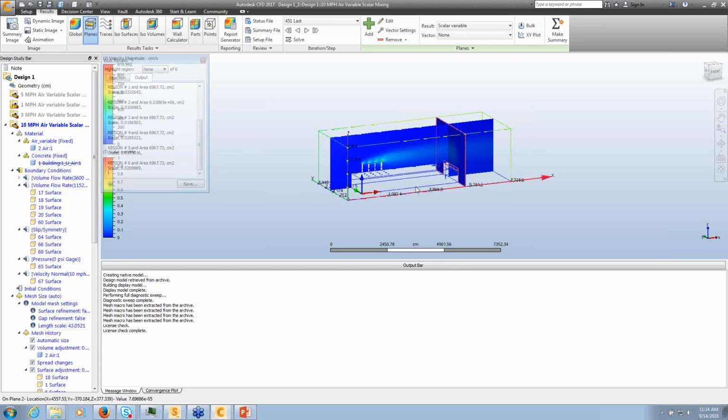And if people are complaining that they can smell the odor from the stacks, then you can think about that. That's probably not going to be cheap, but it has to be something that needs to be done. It's probably easier to make the stacks higher than it is to change the location of the air intake to the building. So that's one example where we are looking at the mixing and looking at the results of the scalar and determining whether we have an acceptable situation or something that needs to be changed.